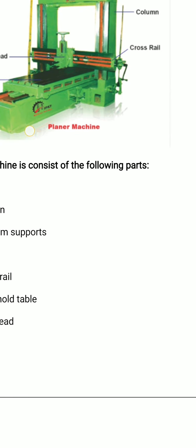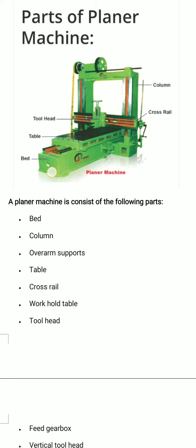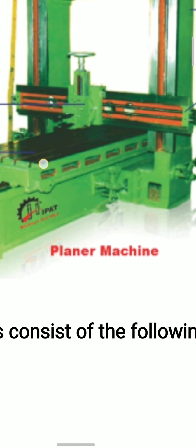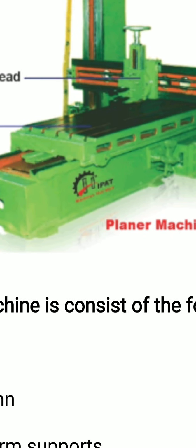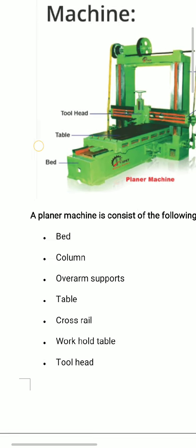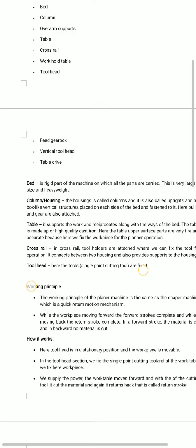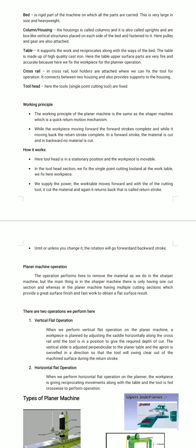planer reversing dogs at different positions. The planer may have a single table or two separate tables mounted on guideways and reciprocates separately or together. Hydraulic bumpers are fitted at the end of the bed to stop the table from overrunning and give a cushioning effect.